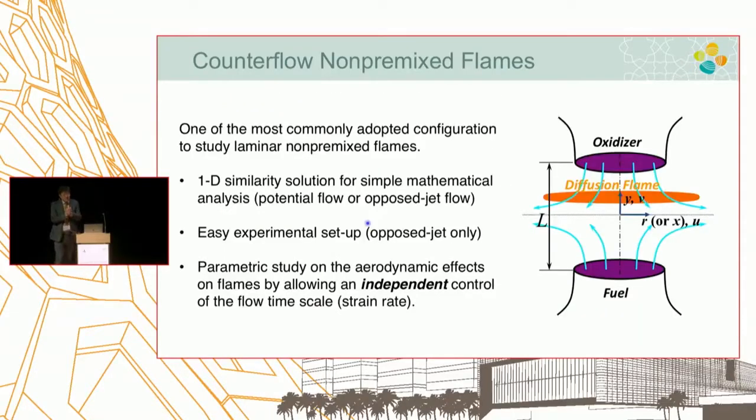All right, so the counterflow system is great in that the Damkohler number, the denominator and numerator, can be controlled independently. How do I adjust the numerator, chemistry? I change the mixture composition, and then heat up the upstream gases and so on.